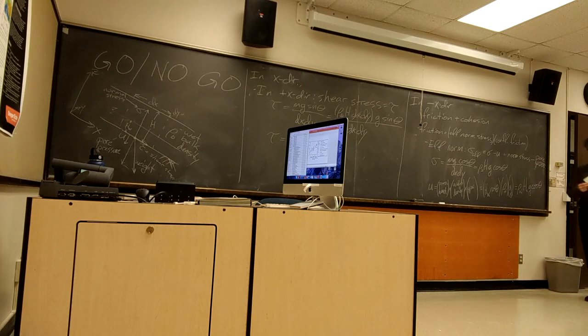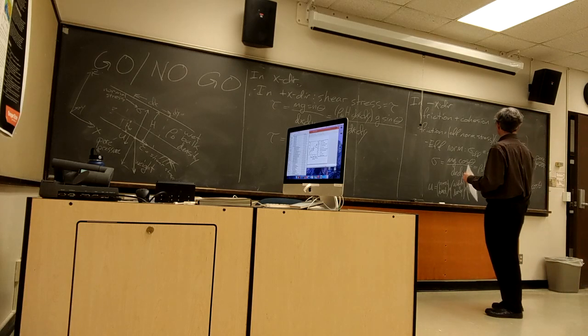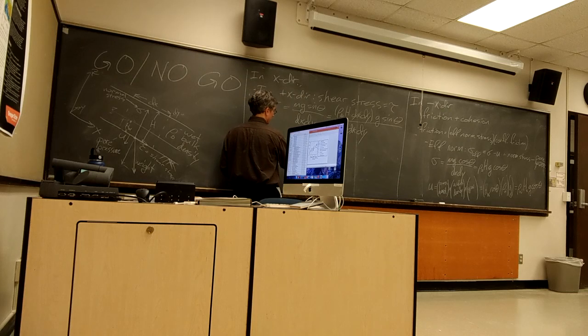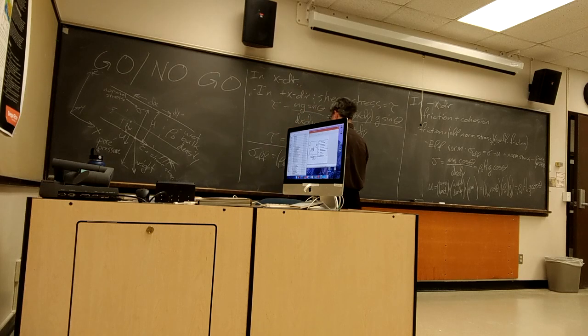So that our effective normal stress is just the difference of the two. And I'll go ahead and combine some terms here because I can gather up my G and my cosine and distribute my bulk densities, my soil bulk density, my density of water, my soil thickness, my water table thickness in the parentheses here.